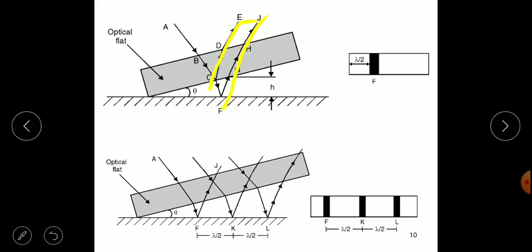So if the distance between these two is odd or even, based on that the wavelength difference or path difference will give the dark and bright fringe. And an important thing to observe the fringes is that there should be some sort of inclination for this, and obviously this is available due to the surface irregularity.